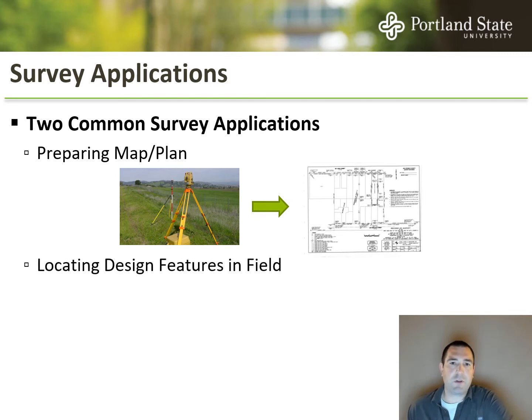But there's also an important characteristic of surveying that goes in the other direction. So let's say that somebody has created a design of a building or a water treatment facility or a retaining wall. When we've designed it based off the survey, we then need to hire the surveyors again to go out and stake out maybe important features of our design so that the contractor can go out there and actually build it.